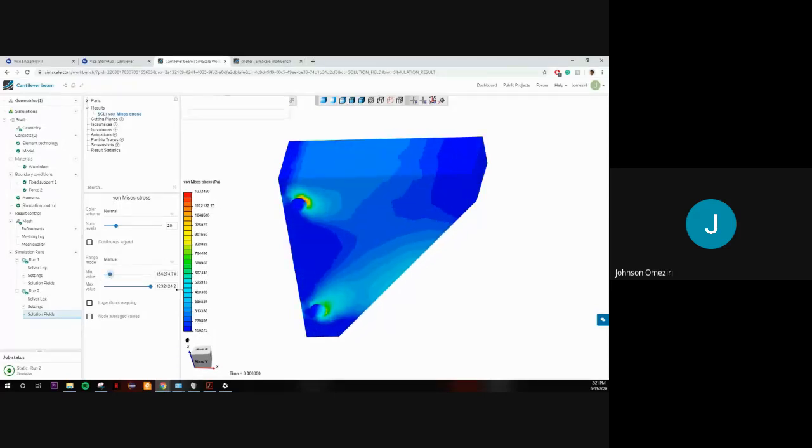So basically this is just telling me where the majority of my forces are being applied. For example, I don't want this to go more than a certain amount, even after I apply my factor of safety. I can see that a lot of this part is still blue. The parts that are still blue mean that I don't really need those parts to support it. So I could do post-processing and literally redraw this and take all those blue parts out. So that's the majority of this.